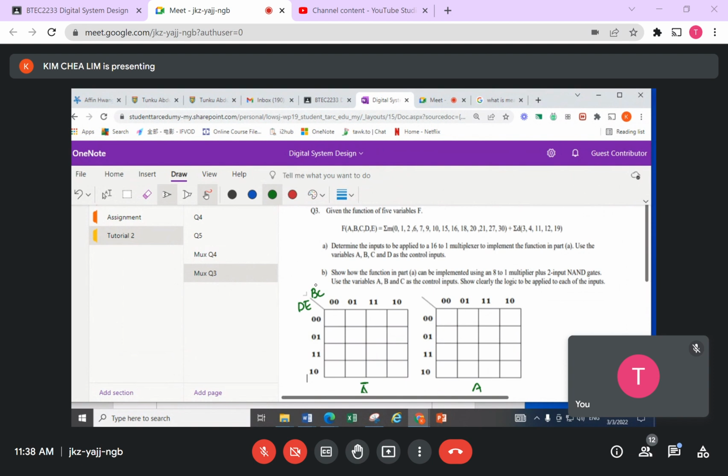So get ourselves familiar first, where is the minterm location? So this is all 0, so I put right small one. So 0, 1, 2, 3, 4, 5, 6, 7. All right, so this one exactly the same as what we usually see. And now A is a 1, therefore 16 is here. So every one of these minterm locations, I'm going to add 16 to it. Of course, 17 now, 18, 19, 20, 21, and so on up to 31.